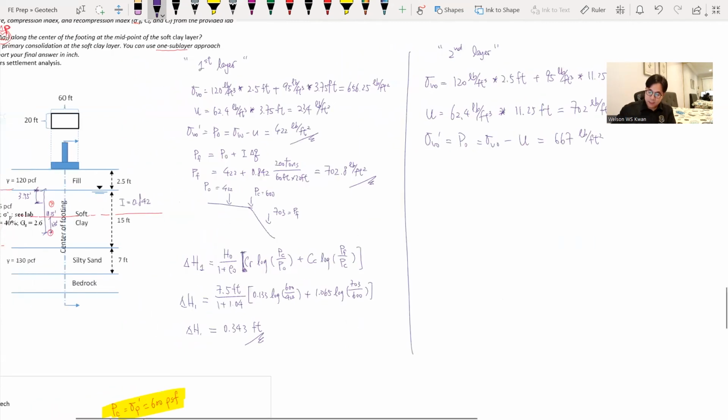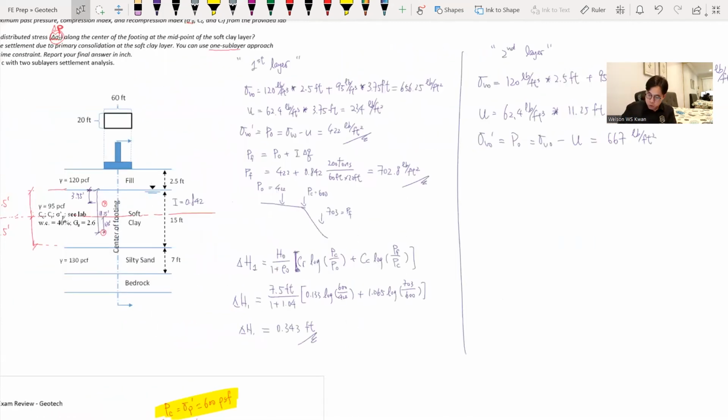And in the second layer, let's assume the I factor on this location is 0.693. Again, I'm giving you those I factors, influence factors, now. In fact, there are a lot of different ways to come up with these I factors, the 2-to-1 method, the DM Navy 7.1 method.